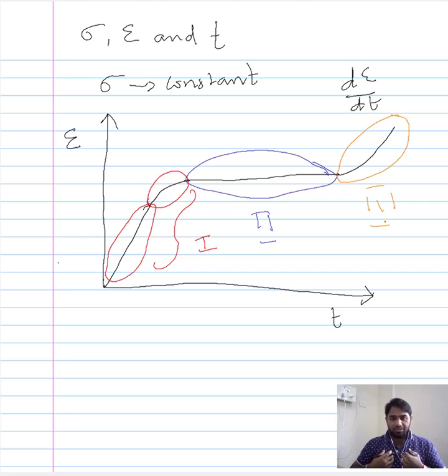We saw that one of the reasons for categorizing the overall creep curve into these different stages is because, in general, the changes in the material that are responsible for each of these stages are different. And so if you want to study this creep behavior in relation to the material changes, then we can relate each of these stages to the material changes, and then it is easy for us to understand what changes bring about this particular stage in creep.